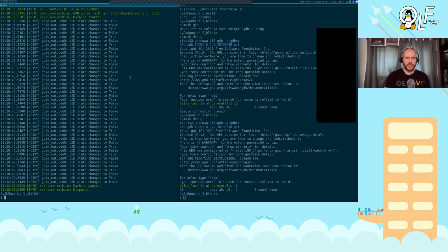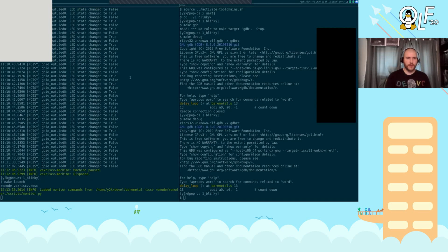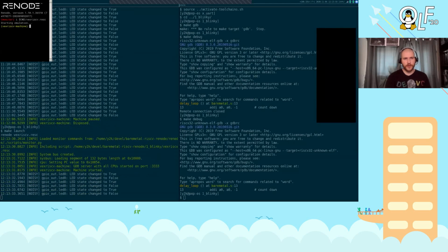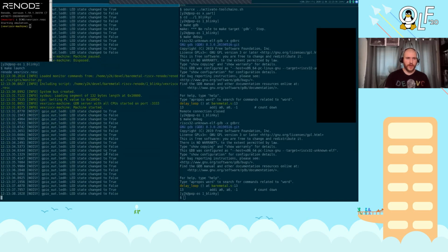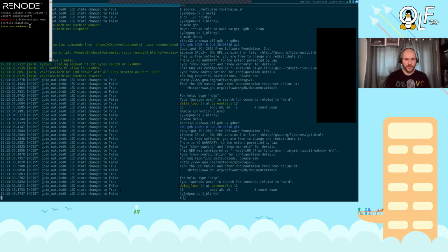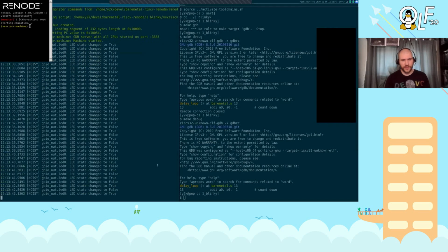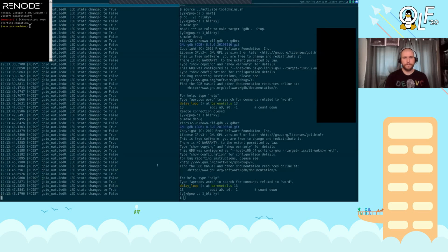So basically, if you pull down my repo, this is the bare minimum you need to get started: you get into the _blinky folder, activate the toolchain and call make launch. You start up the Renode emulator, and this is the monitor terminal that controls Renode itself. And you can see I've turned on logging, and this is the LED blinking. I don't have a physical LED, but I'm logging out whenever the LED turns on and off.